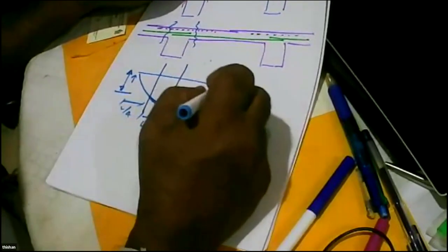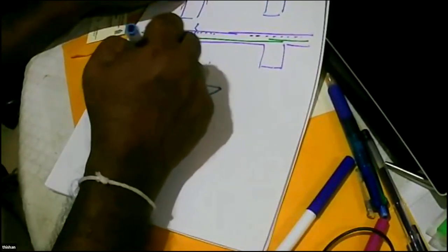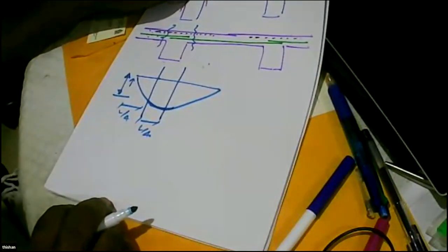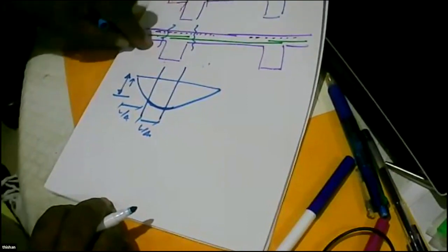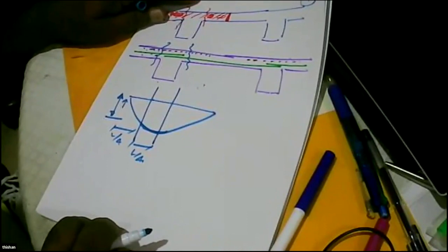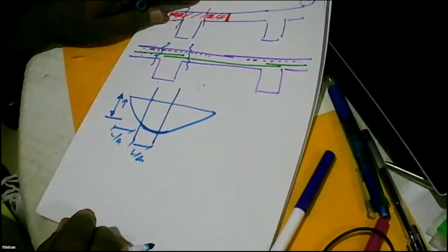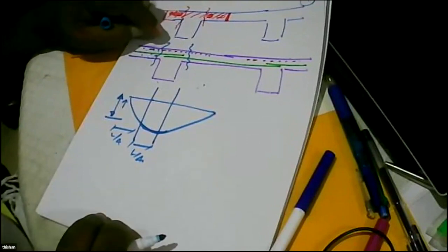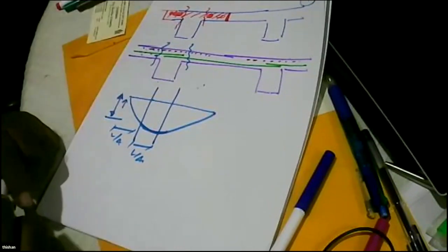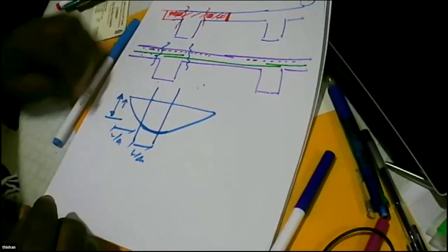Then we find how much force is actually carried in this one between these two points, and that difference in force is the one that caused this shear failure. Then what are you going to say? Check and see whether the shear failure can occur. The shear failure can occur along a beam. Make sure you provide enough reinforcement. So that is something that is available in the code.